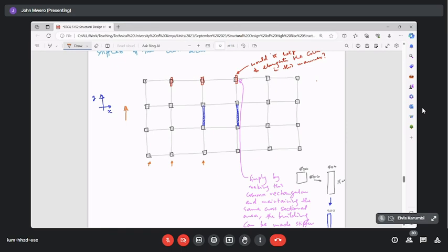But the shear walls are extremely stiff. To these forces, the shear wall is like this wall to the force of my hand. Anything tied to this wall, if I was tied to it and you guys came to push it, and the wall refuses to deform, then I also don't deform. I also don't move with the wall. The wall is a lot stiffer, so much stronger.